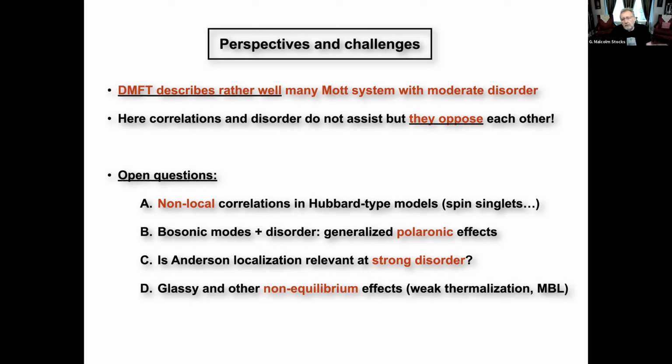But the other thing that's happening in these systems, because they contain metals that all want to be magnetic in some form or another, right? So nickel, cobalt, and chrome. Nickel and cobalt are perfectly good ferromagnets, but chromium is an antiferromagnet. And you're changing the concentration of the antiferromagnet.